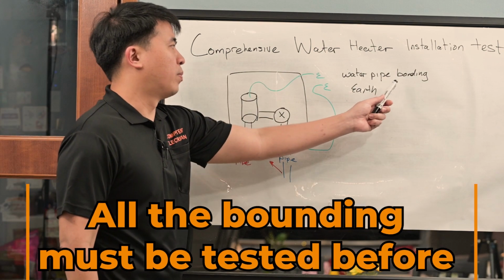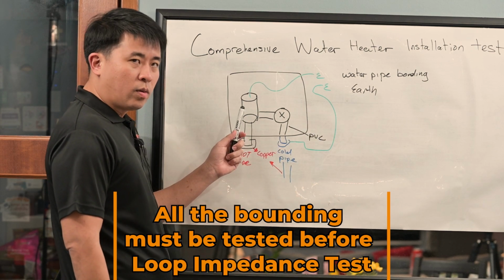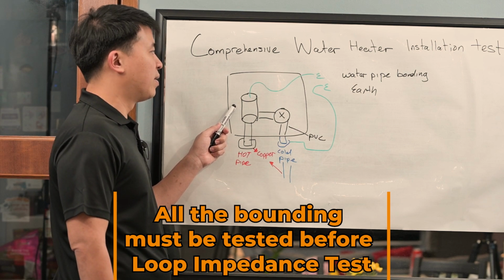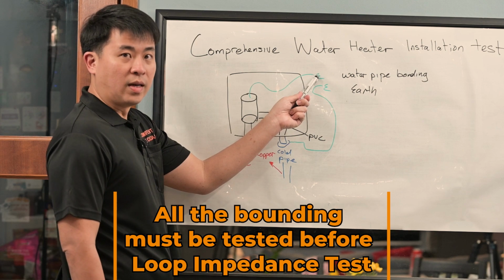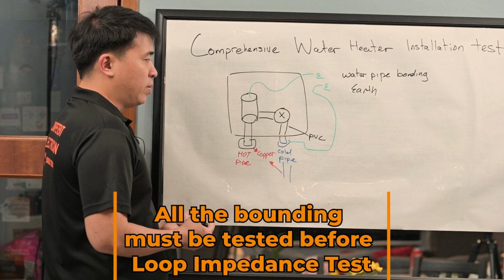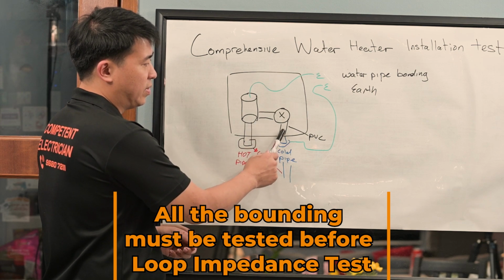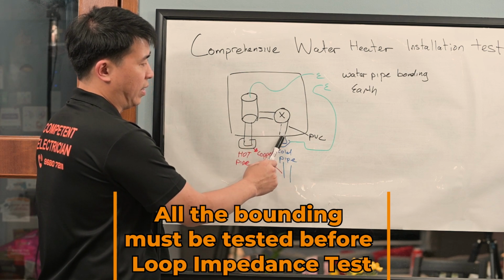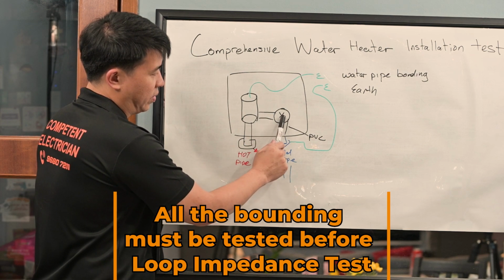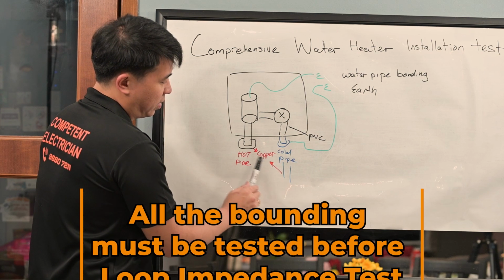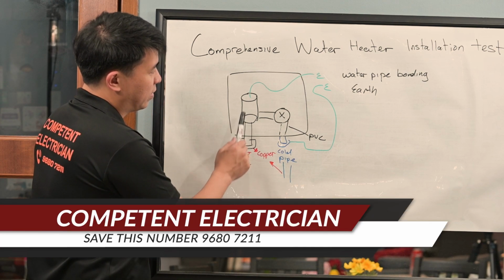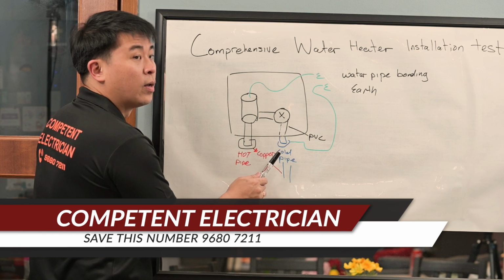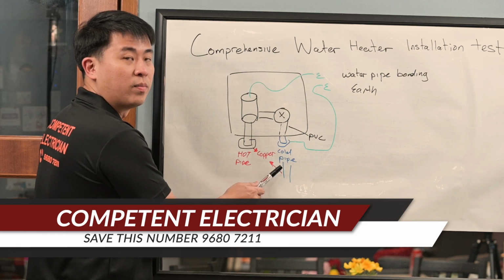Welcome back. Water pipe bond to earth. Normally, all instant water heaters will have a copper tank or metallic tank inside that is bonded to the electrical earth cable. And the technician must check whether there is a PVC or a metallic joint. Some come with a PVC valve, some come with a metallic joint. So this portion itself is PVC. This cold pipe is copper and this is copper. This hot pipe will be copper. So this is to say that here is grounded. This cold pipe could be and could not be grounded.